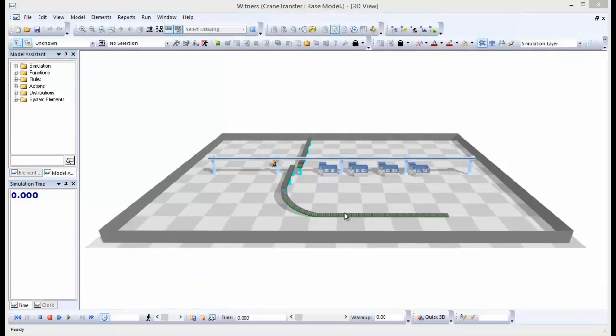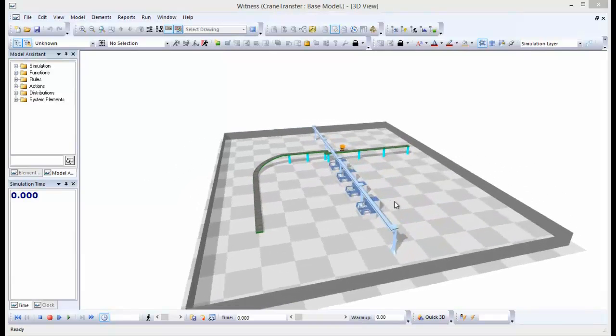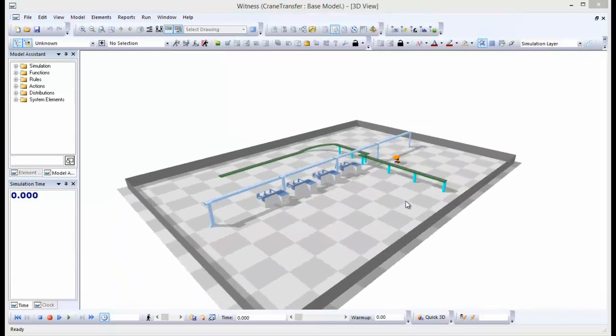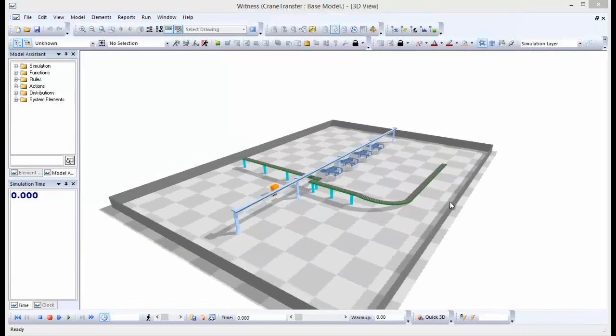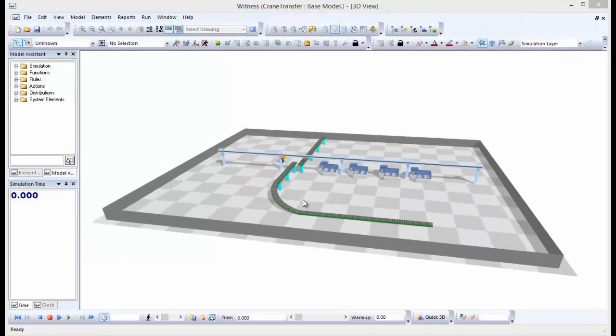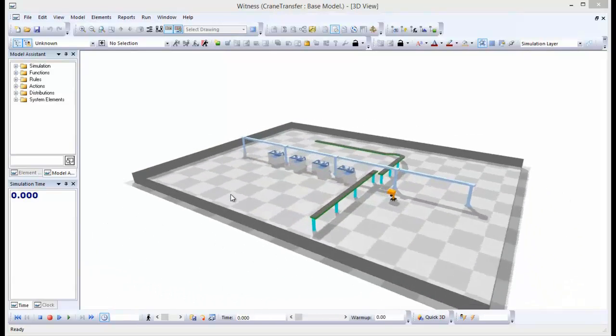Now the next thing I'm going to teach you is to orbit the view, and for this we hold the control key down and then we turn the mouse, holding the middle mouse key down again. We hold it down as we drag it to the right of the view or to the left of the view. And this orbits around the center of the view.